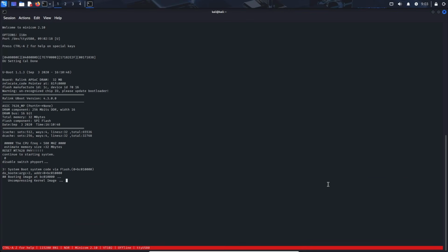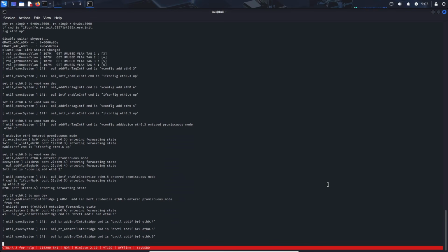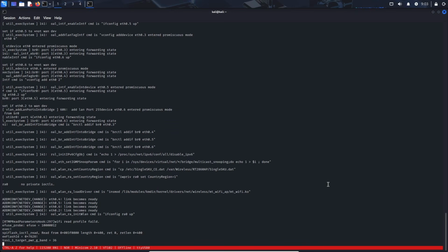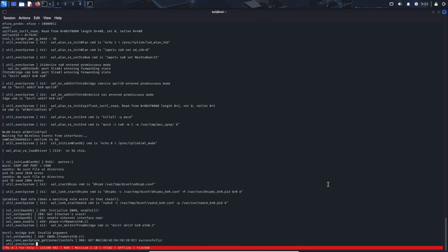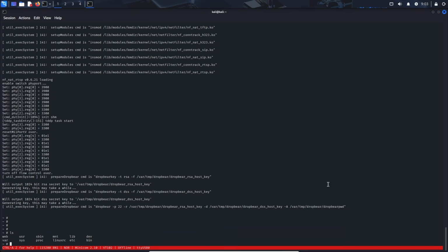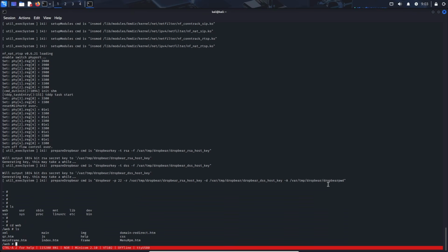And now, unbelievable, we get something. That's actual readable text. So we have a UART connection to the router. I mean, how cool is that? That's pretty amazing. And it gets wilder. So if we press return a few times, we'll see that we have a root shell. So we can browse the file system. See? And even more, we have some tools installed on here.